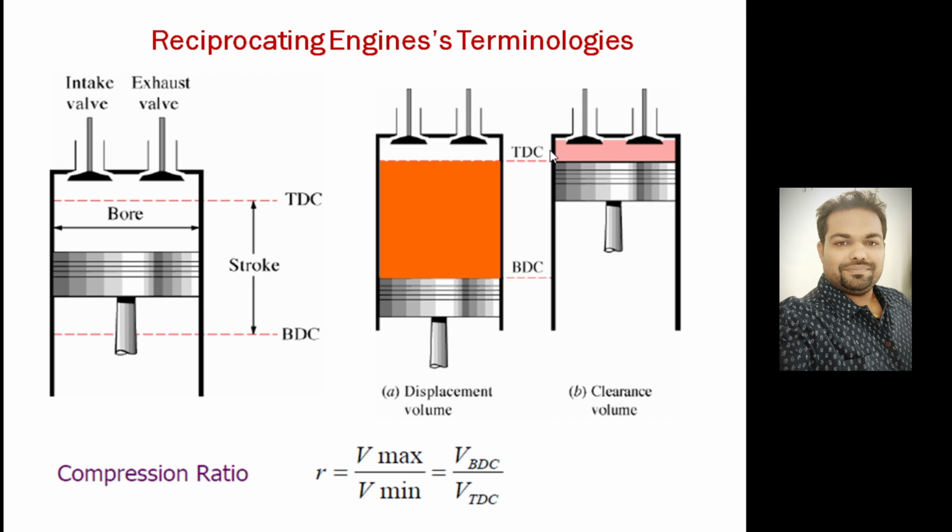So this volume, whatever is left when the piston is exactly at top dead center, is known as the combustion volume, or you can say the clearance volume. Usually in bikes we define 100 cc and 150 cc. That cc is nothing but cubic centimeter, which is a representation of volume. That volume is nothing but this volume. The larger this volume, the larger the heating you can produce. So if you are going for larger cc, it will have larger power output.